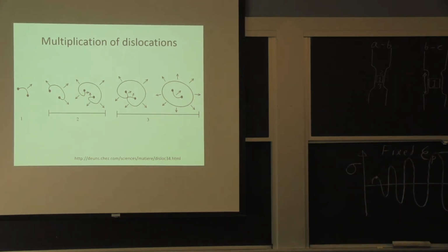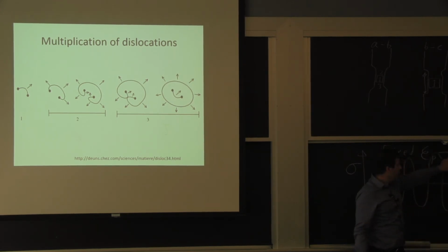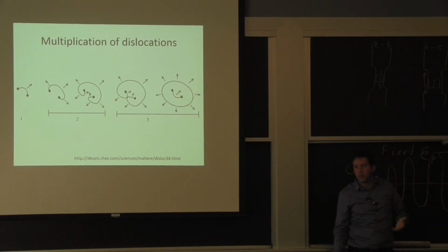The local misfit stresses will make it restore and recover. So if I had two dislocations that were moving in different directions, they're a little bit apart, and I heat it up, eventually they come together and I lost it. Now, when we reach that point here, when we're steady, either by putting a lot of strain or being at higher temperature, the two conditions to get there, it's a point where we have dynamic recovery in the single grain. So we're going to become with a more constant density of dislocations. If you want to amuse yourself with those, you're more than welcome to.